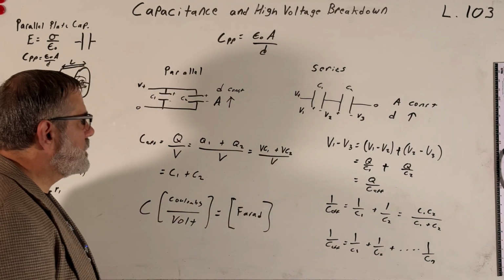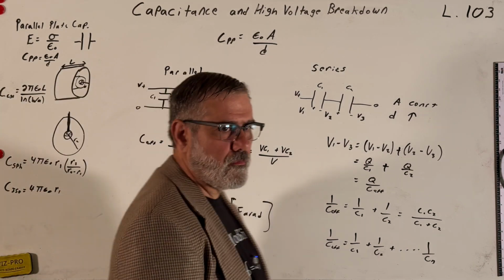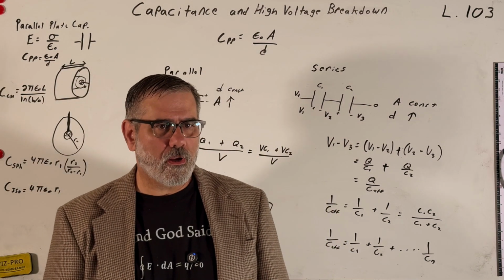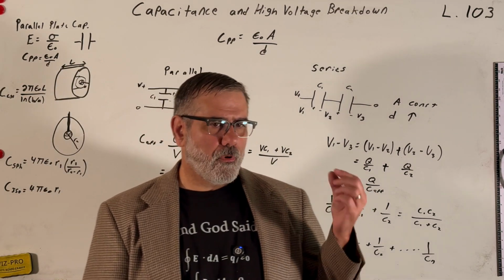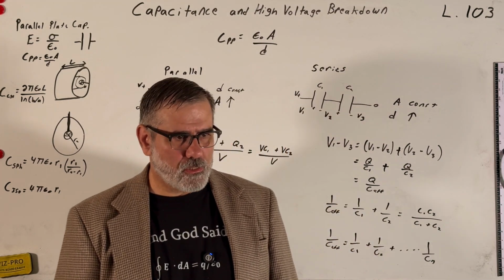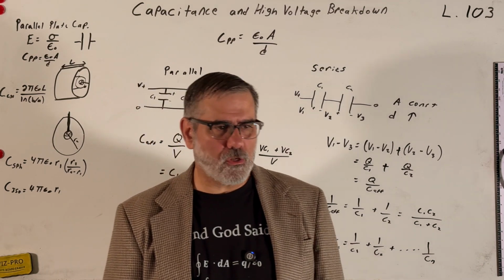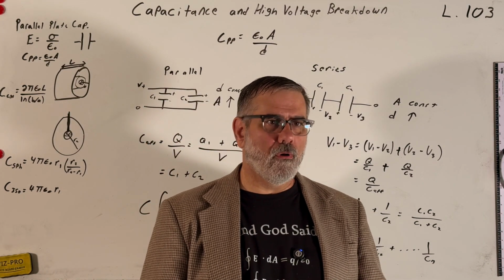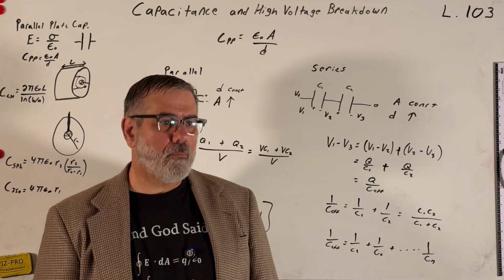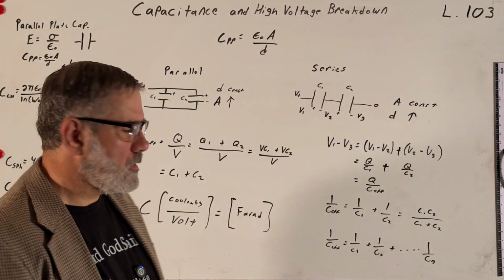Typical capacitances, if we let the surface area of the capacitor be on the order of a square centimeter, and we let the separation distance be on the order of a millimeter, then we're looking at capacitances in the microfarad regime, just to give you an idea. So if you use a capacitor in electronics, it's going to be some number of microfarads at most, probably more likely picofarads, in fact, okay, for smaller capacitors.